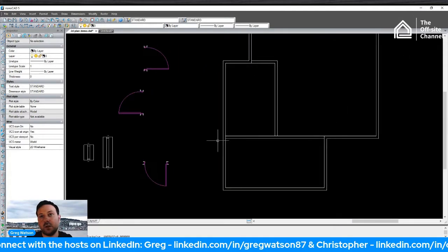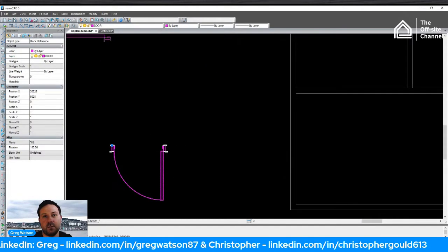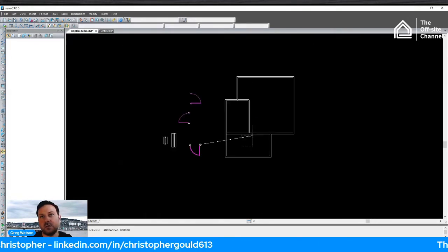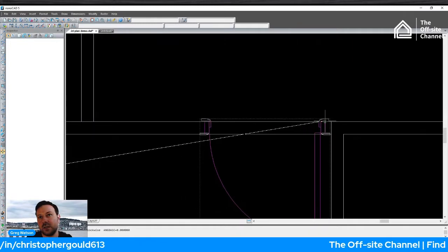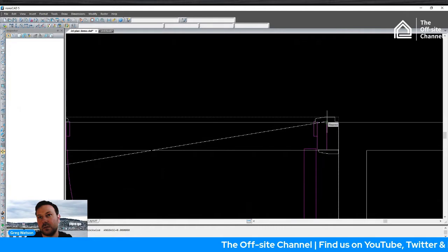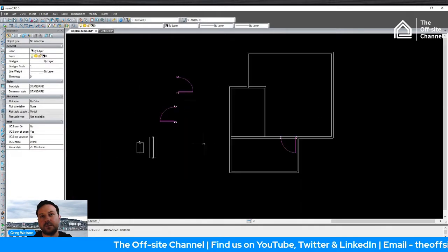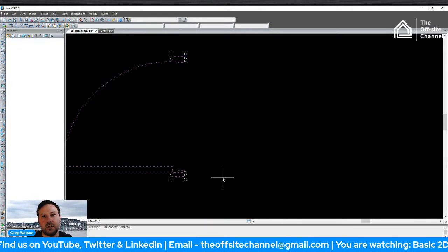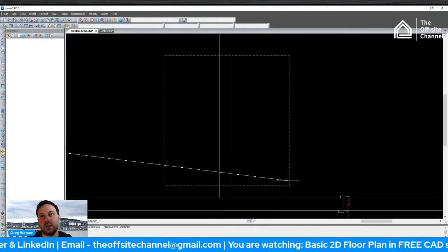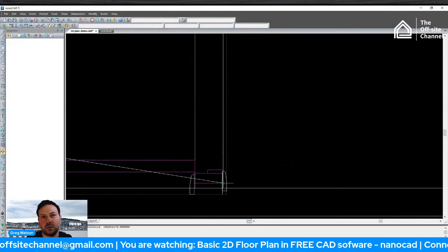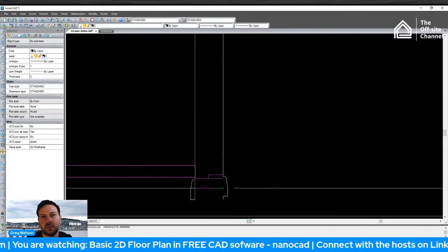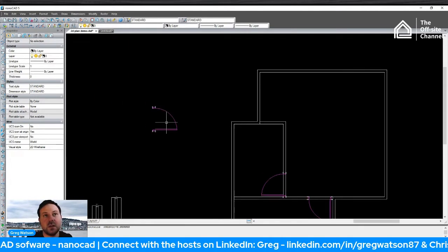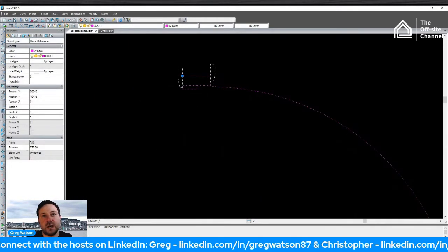So there we go, and I'm going to want to put this here. I'm going to move and not copy this time. So we're going to take that. I'm going to take this door, and we're going to stick it, say, here, like that. That's fine. And we're going to take this one, and we're going to stick it again. Move the object. Right click, click and move, and take it across to here. To that. There's some facings here, but again, I'm not too concerned with that at this point in time. I'm just going to put this on, and then we'll get it hatched, etc.